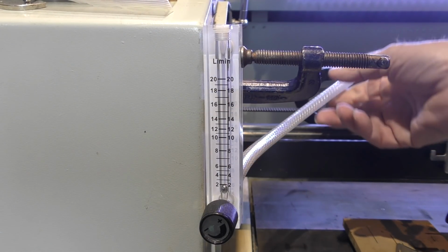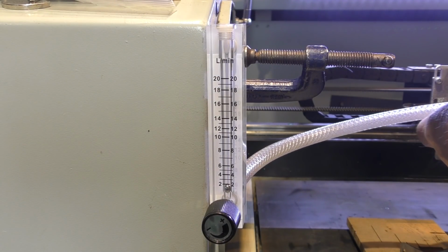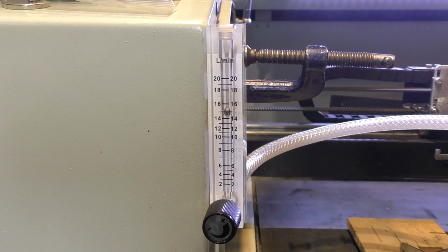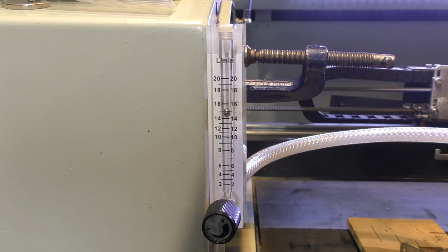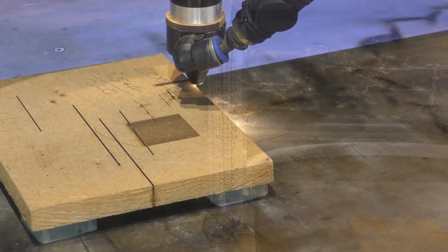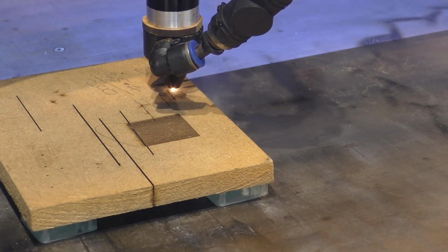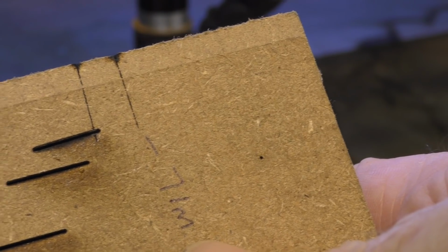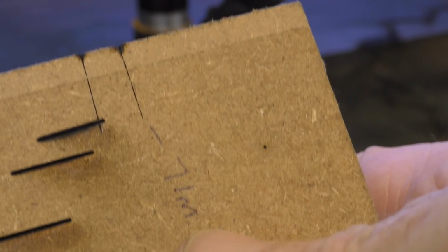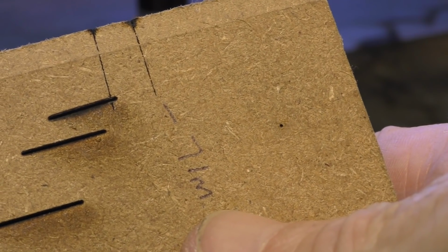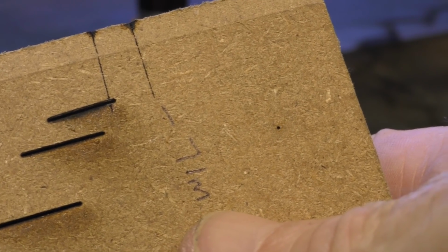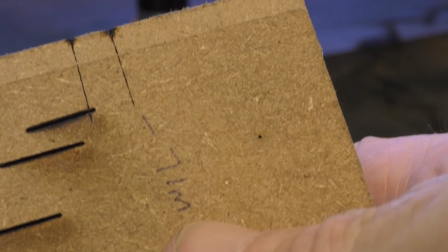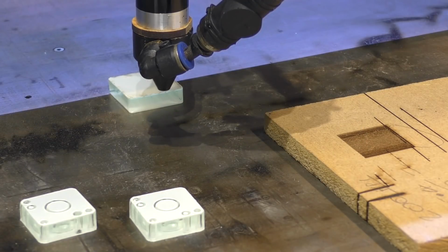Now, if the theory is right, I mean, greater pressure is only going to give me more flow. So I've opened up the valve now, so we're running at about 15 litres a minute. That's twice as much flow. The one on the left has got twice as much airflow as the one on the right. Has it made any difference to the depth of the cut? If the depth of the cut was any deeper, the cut at the bottom would be wider. The answer is no. The cut depth is determined by the lens itself. It doesn't require a sledgehammer to crack a nut.